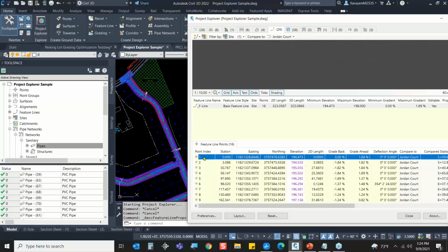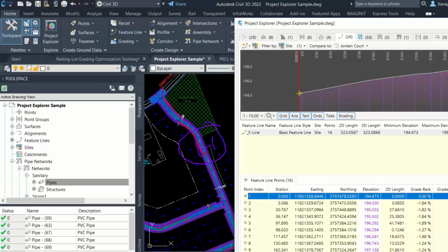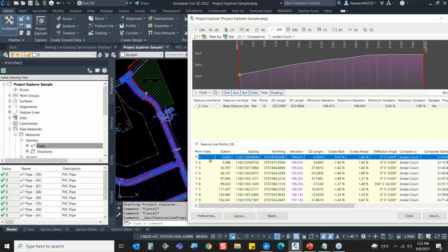And if you notice here on the screen, if I hold my control key, you'll notice that out here is going to give me that distance when I use my control. It's about negative 55 feet to the left. So it pops that value for me as I start comparing these elements. Now, there's just a lot that I can do inside of here.